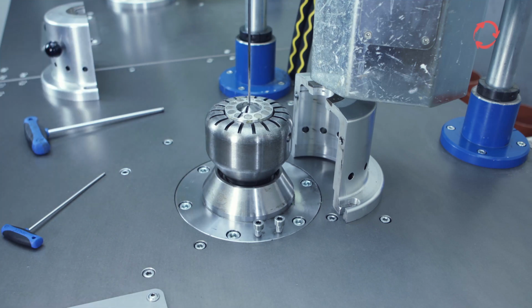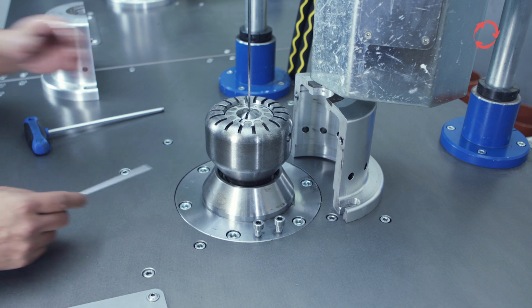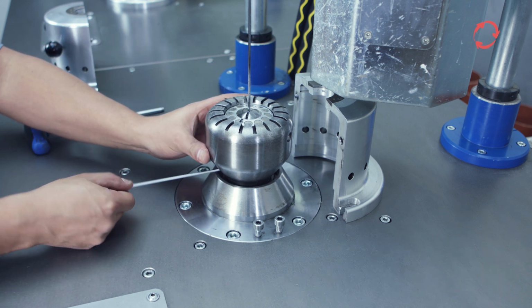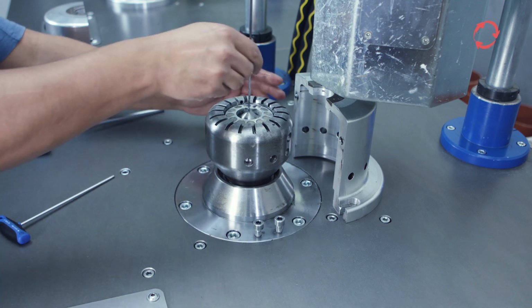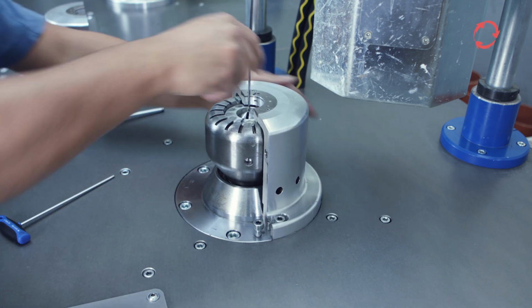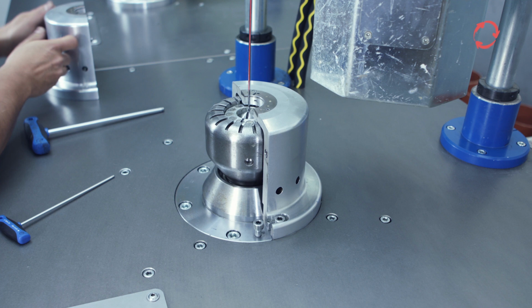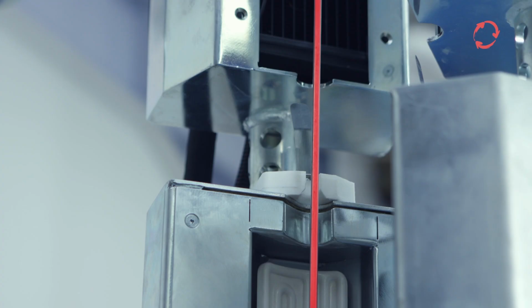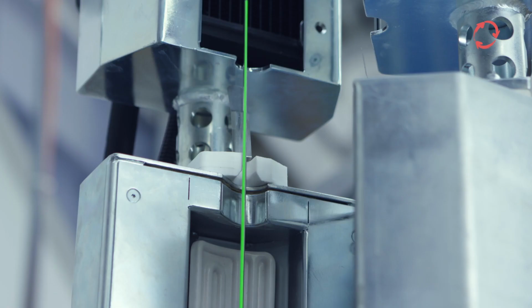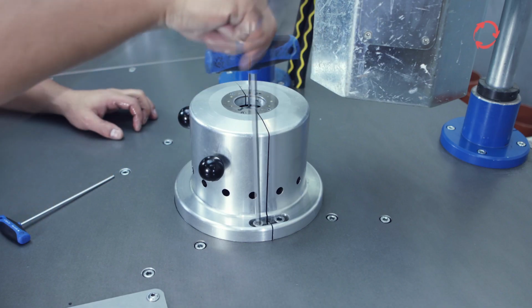Then insert the mandrel intake with the newly mounted mandrel back into the winding head, and tighten the screws on the winding head firmly again. The two covers of the winding head can now be remounted. It should be noted that the alignment of the marking for the mandrel is the same as the position for disassembly. If the mandrel is twisted, it will be in the wrong position when closing the heater, which will prevent it from closing correctly. Make sure that the screws are tightened.